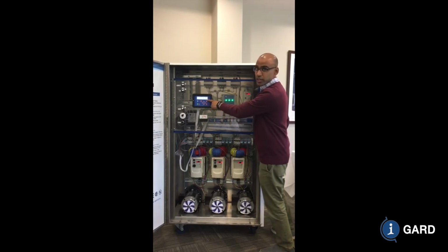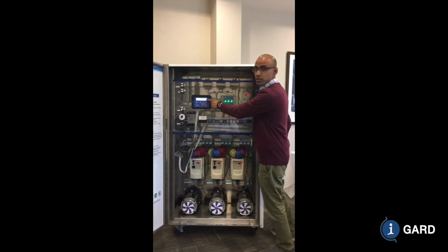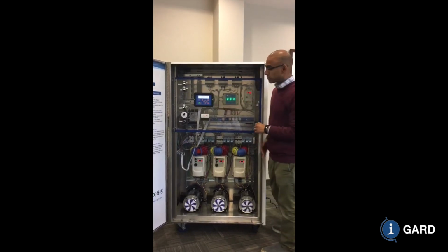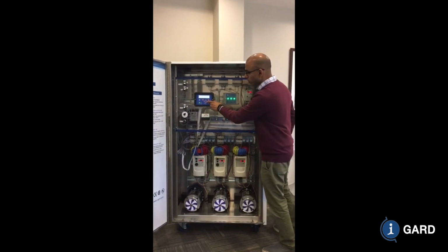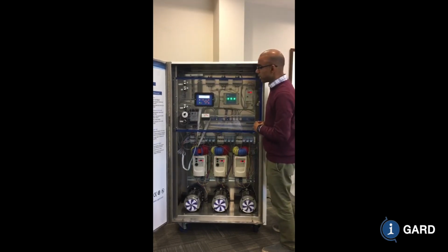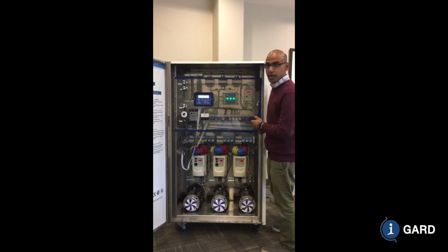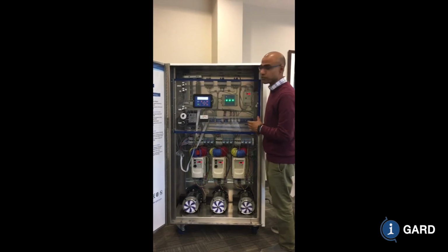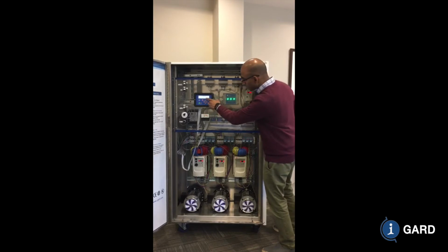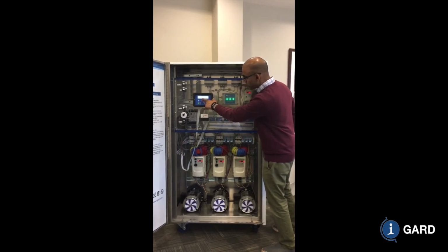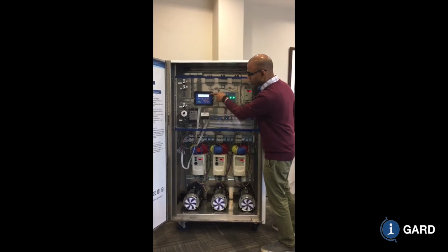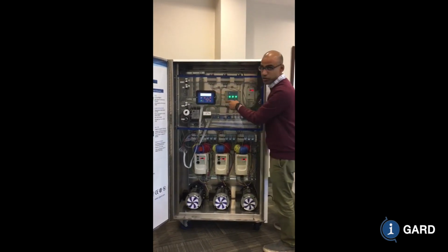It also tells you what the NGR let-through setting is. This is what size resistor you have on the system. Here's the 1 amp NGR. You click another button over, and you get to the feeder module page. Here you can see all your feeders, and you can see how much fault current is on each feeder, as well as their priority setting. So here we're looking at feeder 1, very little fault current if any, and it says status okay, and it tells you that its priority is priority 3.